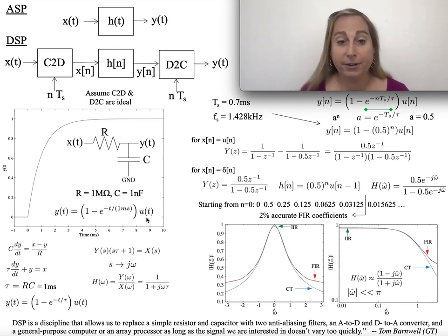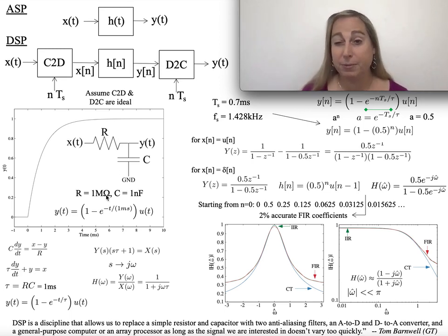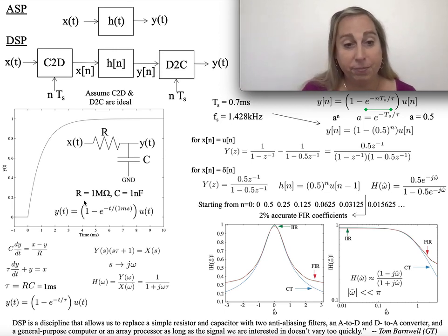And for those of you trying to figure out how to derive a couple of the properties of this, you could write KCL at this node, and you would notice that you get C dv/dt equals (x minus y) over R. I'm using x and y here to be somewhat abstract in these variables, also consistent with up here. These would probably be voltages, normalized as, say, 1 volt. And so there you go.